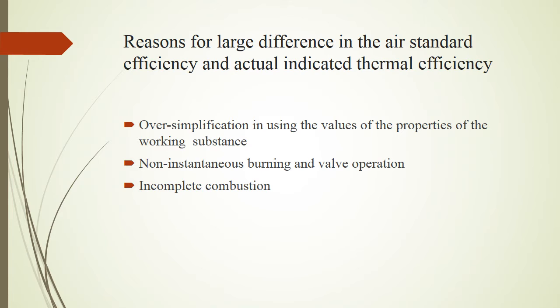In the air standard cycle we assume the substance to be air, a perfect gas with constant specific heats. But in the actual engine the working substance is not air, it is a mixture of air, fuel and residual gases, and the specific heats are not constant but increase as the temperature rises, and finally the products of combustion are subjected to dissociation at high temperatures.